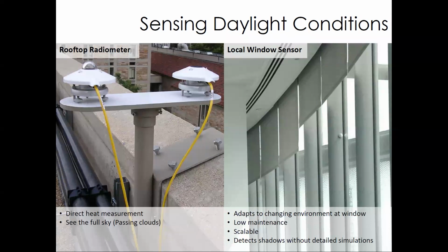They're generally mounted indoors to make rezoning or remounting simple. And most importantly, these sensors are highly adaptable by measuring local conditions. So they automatically adjust for changes in the surrounding environment, such as cloud coverage, shadows, large reflections, etc. These devices also are not affected by low-level fog conditions that may shadow daylight on lower floors, but not affect higher floors.